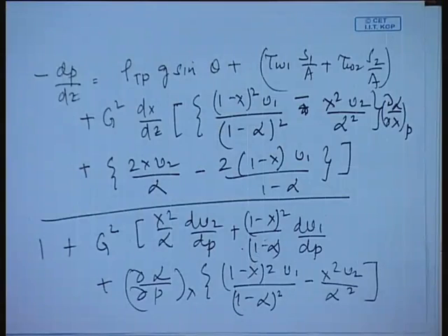What else can vary with pressure which we have not considered here? Something else can also vary with pressure if you see this particular expression. I cannot give you much time to think, that is the tragedy here. I have taken dx/dz to be constant, or in other words, x does not vary with pressure. When does that happen? It happens under ordinary circumstances in the absence of flashing. So in this case we have assumed that flashing does not occur.